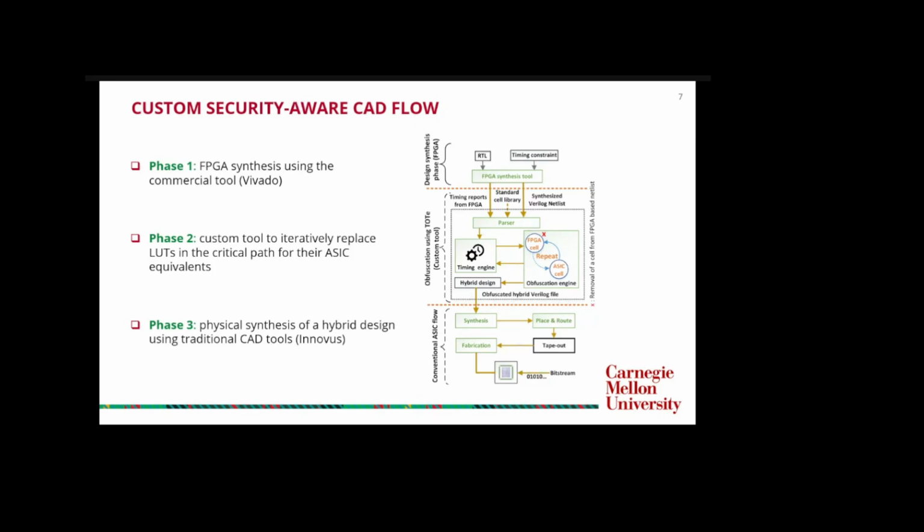If you know the FPGA architecture, we have CLBs. In the CLB, we have a carry block, we have lookup table, we have flip flop, we have mux. All these primitives combine and make a configurable logic block, we call CLB, right? So we try to identify that, and then we try to identify the critical path. The critical path is the worst path in the design, I mean, the slowest path in the design, right? And then we try to ignite our obfuscation engine.